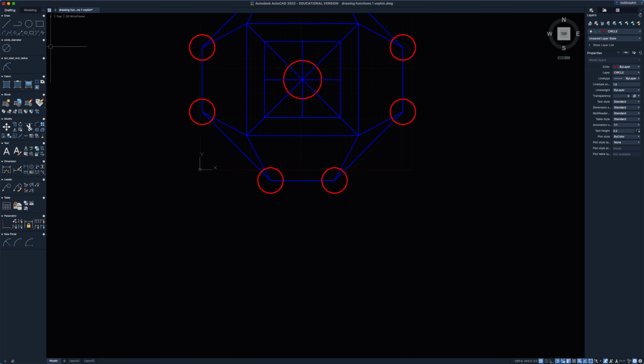So luckily, if I go over to the tool set and left click on the circle, it brings up 6 other ways that I can make a circle. So I can do center diameter, 2 point, 3 point, tan radius, and tan. We're going to do tan radius. So it says in the instructions, what's the first tangent? Right there. What's the second tangent? Right there. And you can see that the number 75 is in there, indicating the radius, because that is the dimension that we last used.